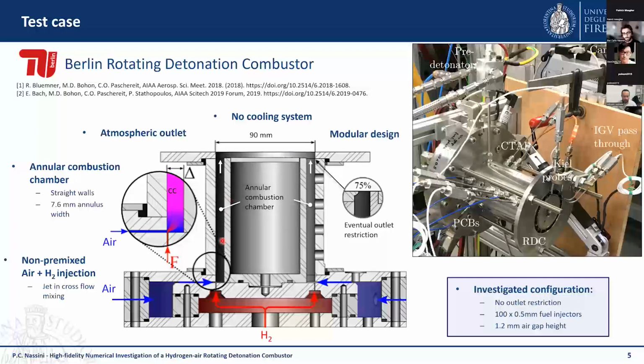The combustion chamber is a simple straight-walled annular combustion chamber, which is open to the atmosphere. So we don't have pressurization of the system, but also we don't have a cooling system of the combustor. So the operation is typically limited to a few seconds.